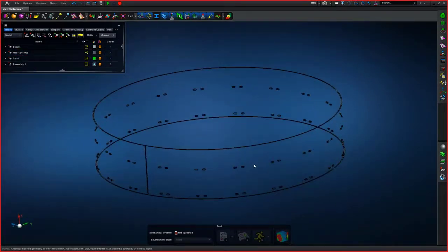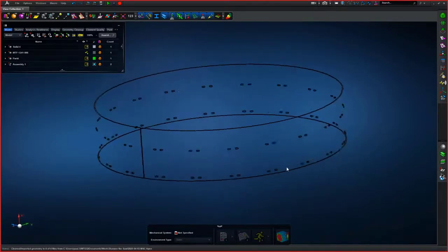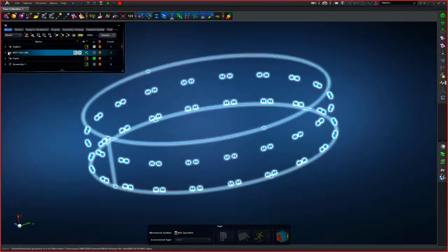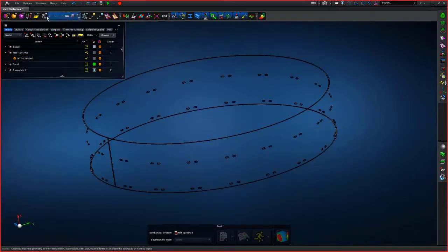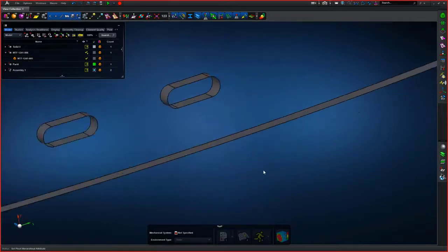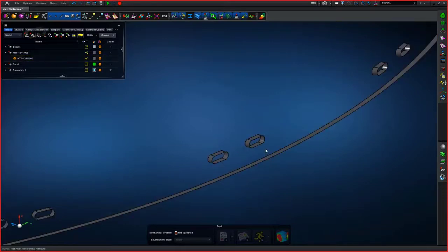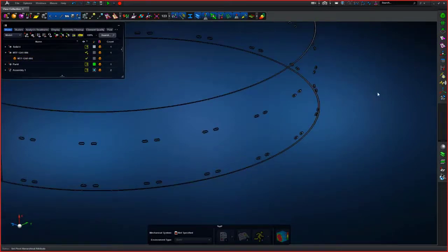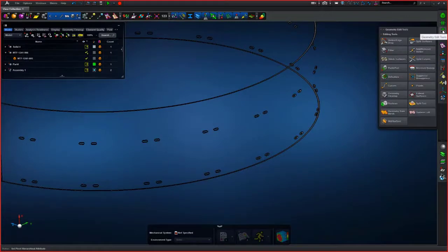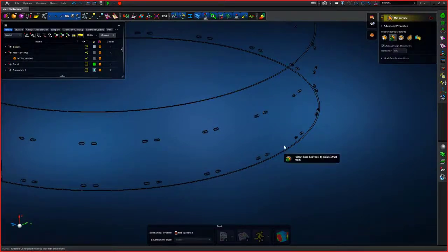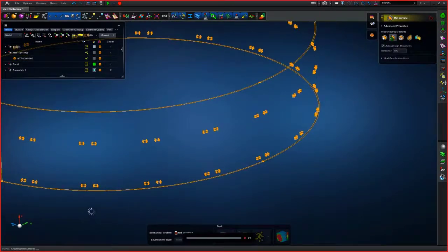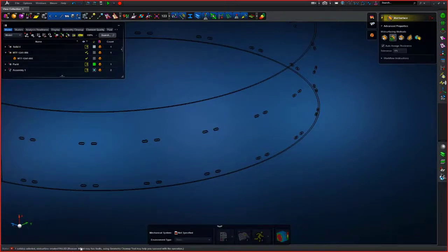So this is a CAD file that came in and was clearly in a broken state. It is supposed to be a solid, and in the model tree it is actually registered as a solid, but there's clearly something wrong with it. As you can see, we only see the outline faces of this solid. One of the ways that I also found that this thing is definitely broken is when I attempted using the mid-surface tool on this solid, it flatly ignored me and failed. Over here at the bottom, it showed that it failed, and the reason is that it has faults.